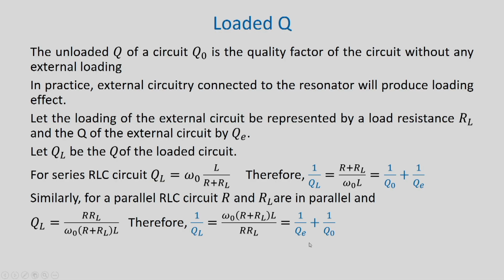So, once we know the unloaded Q of the series or parallel RLC circuit, and we know the external loading, that means RL, we can find out the Q of the loaded circuit. So, we have studied series RLC and parallel RLC circuits, and particularly how such circuits behave near their resonant frequencies.